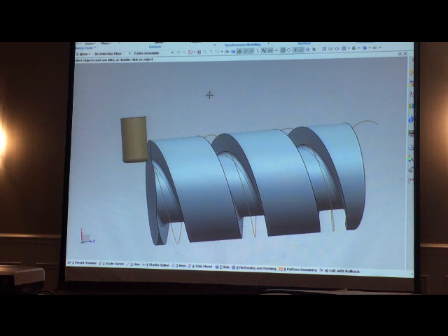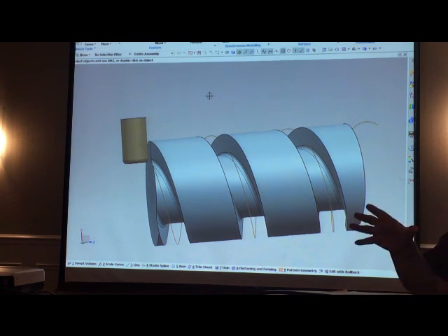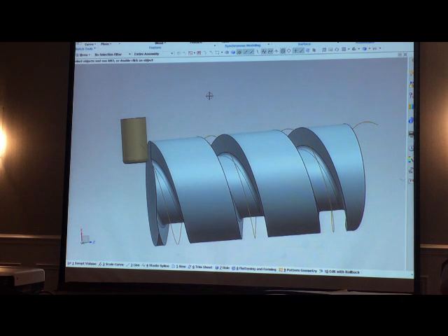Now it turned out that when I was working, we didn't have to worry about this because we had a special machine tool, it wasn't NC, excuse me, it was all mechanical, to build these cams for us. So we did it all mechanically. But then we didn't have a whole lot of variation in it. It was just different lengths, different diameters, different pitches, different size rollers. And we could set that up in this particular machine tool.